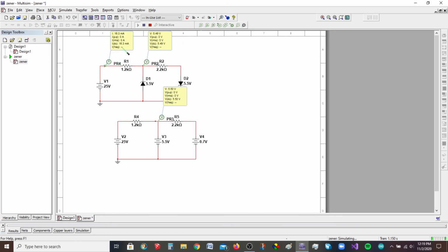Let's see what the current is here, 16.3. Let's see what the current is here, 16.3. So I'm pretty sure we figured out that this was 19.5 volts across this 1.2K. That looks to be correct. Let's go ahead and add some more in here. We expected 2.18 milliamps, and then we have 2.24 milliamps. I said we'd be just a touch off because of how we had to round up that one number, the 16.3, okay? So let's go down here and see if we have the same thing. Okay, so now that matches more closely what we have here.